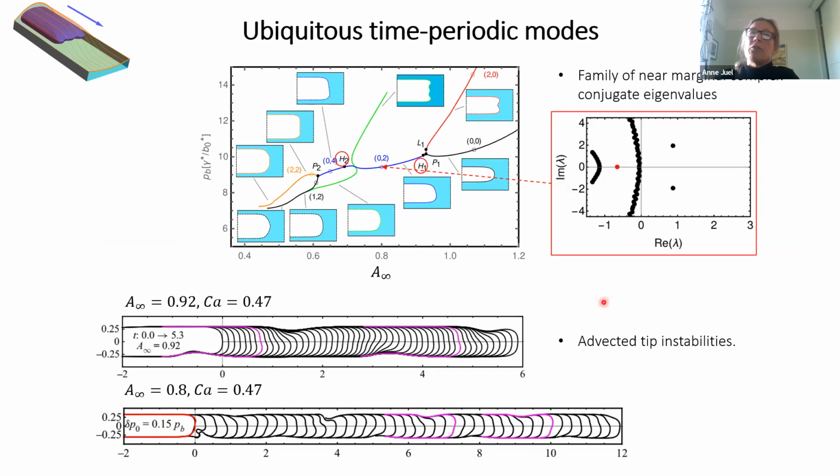And really, this is just to emphasize this a bit further. We can look at the bubble pressure as a function of the level of collapse, and here, at a reasonably unperturbed initial cross section of the channel up here, we're very much in a similar system to the rigid Hele-Shaw system. But as we collapse the system further, we go through a variety of bifurcations, and you have two Hopf bifurcations. So really time dependence is ubiquitous